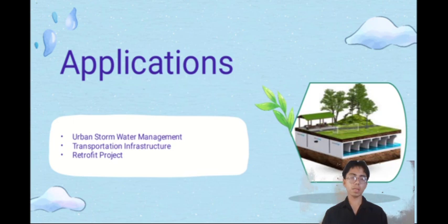In summary, stormwater detention is a critical tool in modern stormwater management systems, offering effective flood control and protection for downstream infrastructure. While it is not designed to reduce runoff volume significantly or enhance water quality, its role in attenuating peak flow and preventing urban flooding is indispensable. By integrating detention systems with complementary practices, communities can create resilient and sustainable stormwater management systems, a solution that addresses both immediate and long-term challenges.